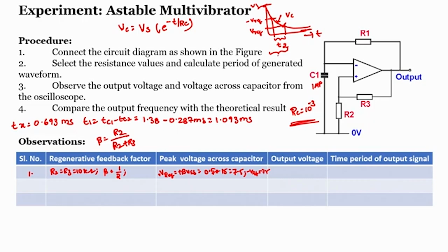So I am calling it TDC2, the discharge time, as with TC1 previously, from plus 15 to minus V reference, right. And again I can calculate the time duration from plus 15 to plus V reference, meaning plus VCC to plus V reference, as TDC1. Since I want to know T2, T2 I can write down as TDC1 minus TDC2.